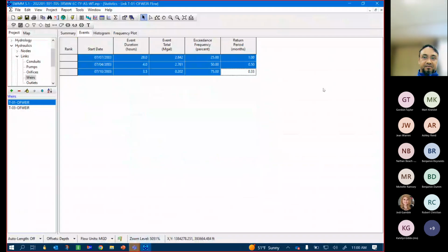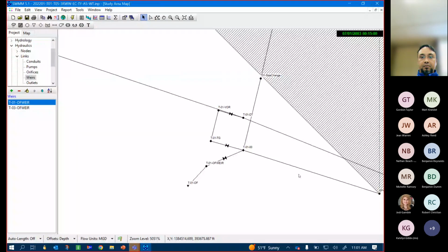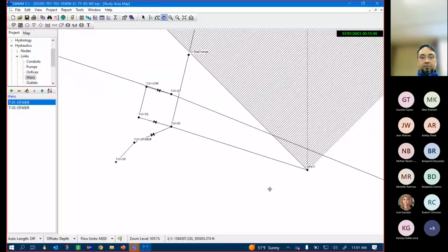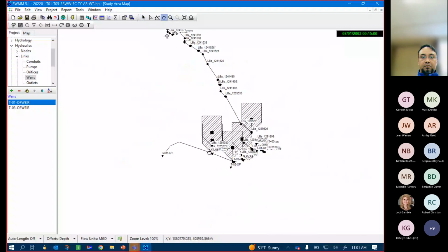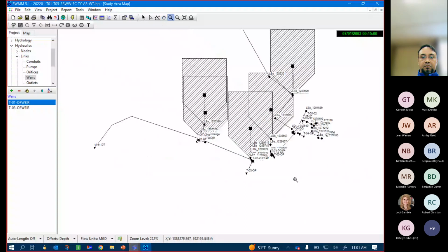I just wanted to add one thing to what Colin said when he identified the link. As part of the TMs that we provided on the percent captures, we identified the links that we actually use to calculate those volumes. So I would highly recommend that you go to those TMs, pull out those links, and those are where you calculate it. There are different places you can grab it, like the weir or the outfall pipe. You will get slightly different answers depending on which one you use. Sometimes there are backwater issues that make it difficult to quantify it. So I would recommend using the same ones that are within that TM.